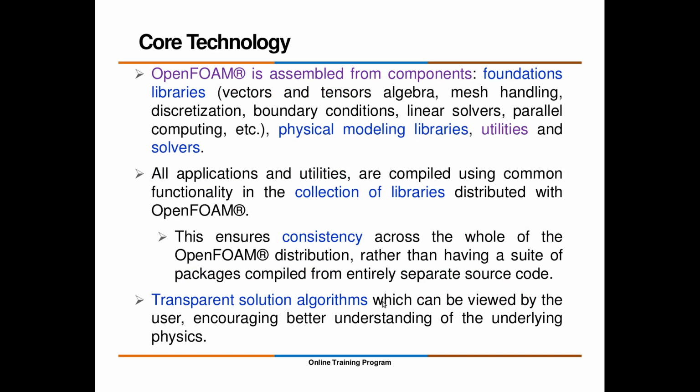If you look at the entire OpenFOAM, it is assembled component-wise. The fundamental libraries or fundamental platform are available in terms of vector and tensor algebras, mesh handling, discretization methods, boundary conditions, linear solvers, and a parallel computing environment.